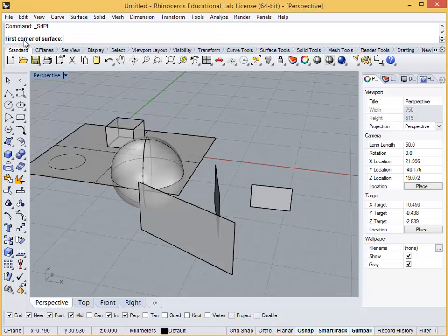Like AutoCAD, Rhino has a command bar that accelerates how efficiently you can work within the software. Many of the commands are similar, but not quite the same as AutoCAD, so be sure to keep an eye on the command bar as you work. You can modify the Rhino keyboard shortcuts so that they match the AutoCAD exactly. Google this to get instructions for your make, Windows or Mac, and the version of Rhino.